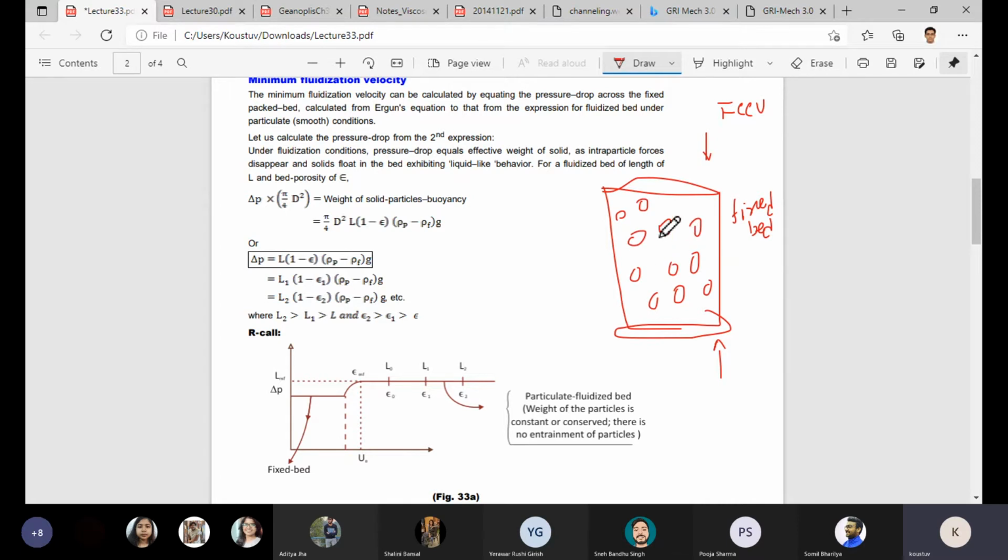So what advantage do we get? Typically in fluidized bed operations we get a high rate of mass transfer or heat transfer. That is very essential in heterogeneous kinds of reactions. So there is good heat control. In packed bed or fixed bed operation, we often encounter hotspots, which are not desirable in operations. In order to overcome them, the bed is treated as fluidized.